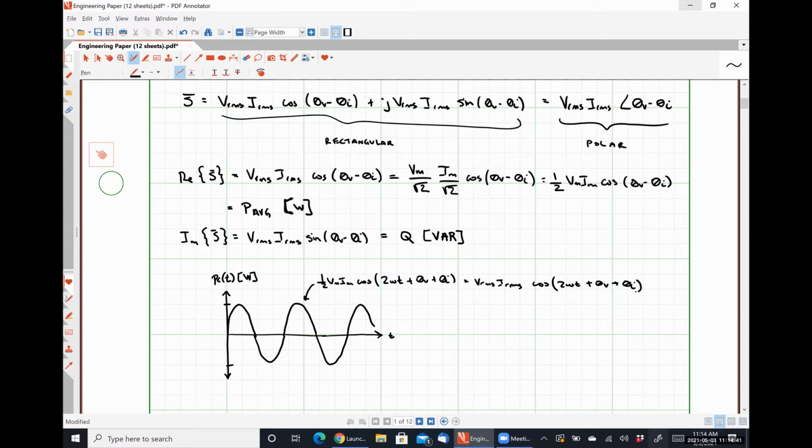So a common question that I get asked is, if reactive power just represents power being transferred back and forth, then why have it at all? What is it used for? Reactive power is used in electricity distribution and in electrical machines. In electricity distribution, reactive power is injected or absorbed to maintain voltage levels when demands on the power change. So they are a form of temporary energy storage, because capacitances and inductances, which we have seen throughout Engineering 221 and this class, are short time energy storage devices, right?